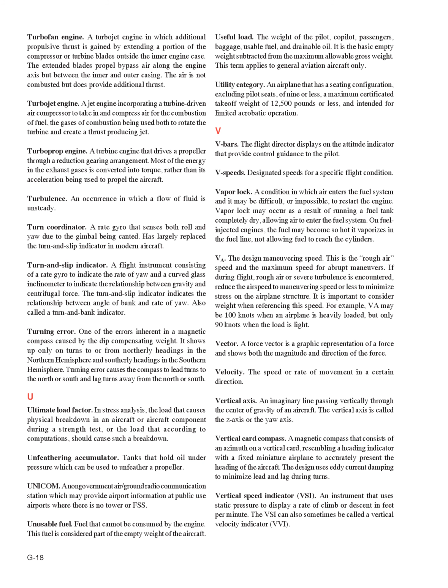Vertical card compass. A magnetic compass that consists of an azimuth on a vertical card, resembling a heading indicator with a fixed miniature airplane to accurately present the heading of the aircraft. The design uses eddy current damping to minimize lead and lag during turns.